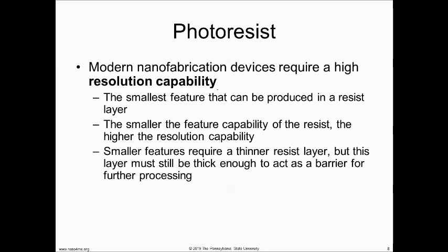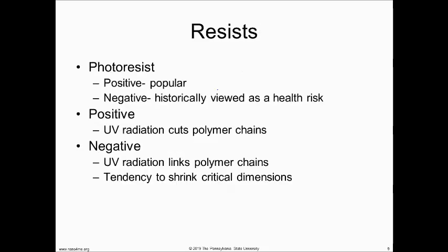With contact lithography, we're going to be able to make things that are about 1/3 of 1 micron, the base dimensions on a transistor. Does that make sense? And again, as a review, a hair is around 100 microns, and you could probably see 30 microns. Now we're looking at 10 times smaller than you can possibly see with your vision. Does everybody see that? So these are very, very tiny, and that's about as small as we could make with this contact lithography method.